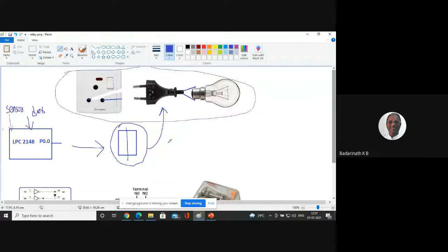Yes or no? For low voltages and low current, that is okay. If it is 12 volts, 8 volts, 6 volts like that, I can use a transistor. But if it is a higher voltage, let's say 220 volts, 48 volts, or 110 volts, then the normal transistors available, or whatever you use in circuits, cannot be used. You can use ULN2803 or a normal SL100, but I cannot use it here. Why? Because I have to operate high power devices. I'm not talking about 6 volts or 12 volts, but a high power device at 220 volts.